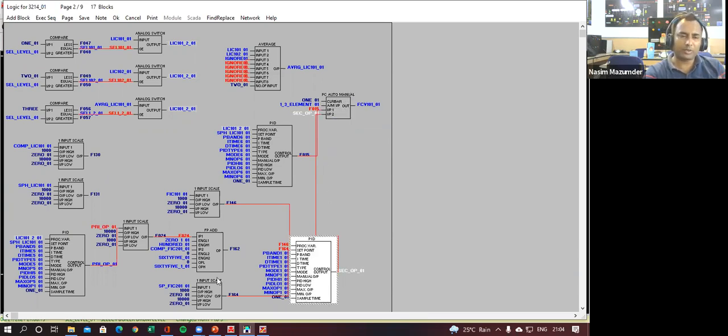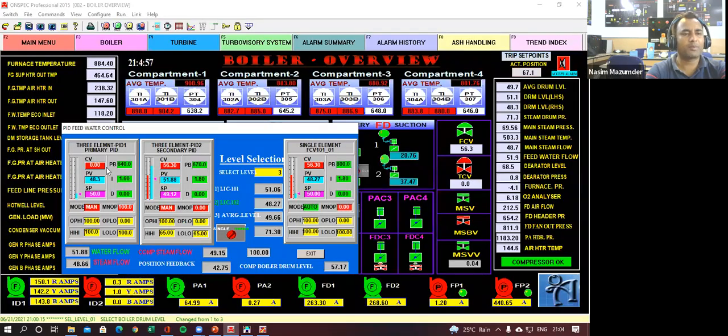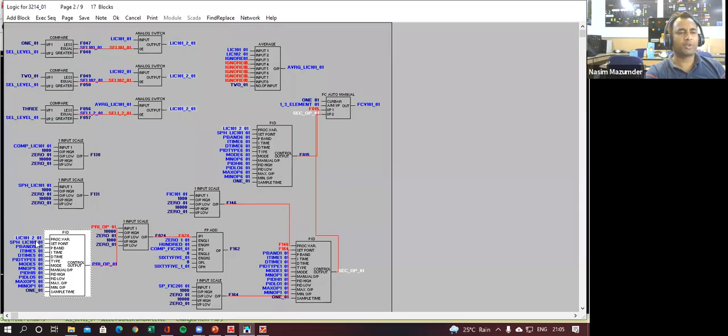And all the calculations have been done here. So this is my secondary PID, and this is my primary PID. You can see here, one is your primary PID, another one is your secondary PID. Any changes you make here, this PB or D, will be coming here, PB or D. Then this will be fetched to some scale.